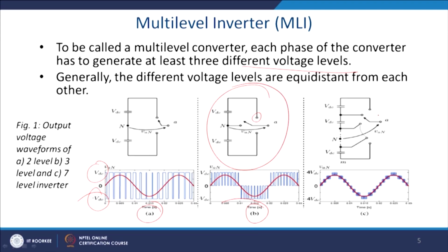So, this is generally what we also call the multi-level inverter, or the 3 level inverter. And in a multi-level inverter, you can have different levels and you can split this voltage like this, and ultimately you generate this waveform. You can see that it has a very low dv/dt, and the number of switches required will be more, but it is very close to the sine wave, and the requirement of the filter will be reduced. Low dv/dt, all those advantages will be there. And since these switches have to block only VDC by N of this total voltage, the voltage rating of these devices is also going to be reduced.